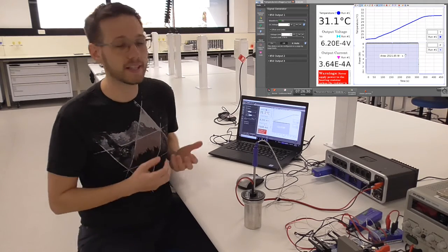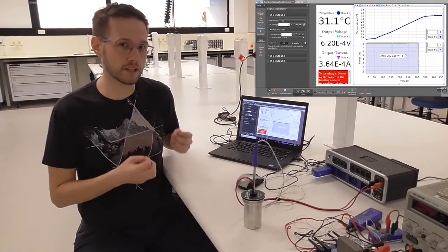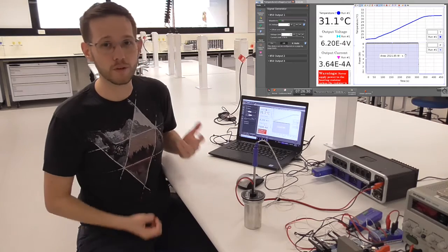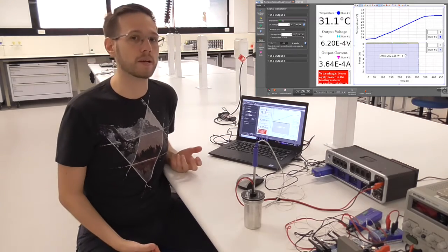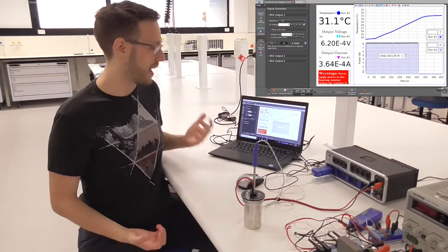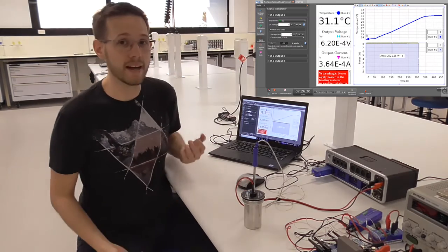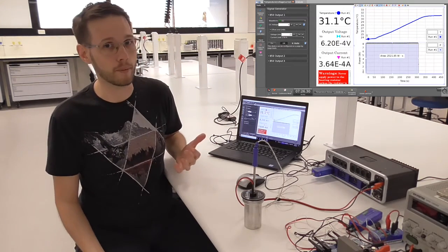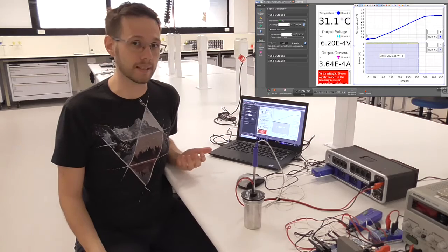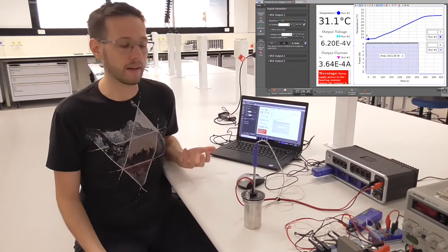So what we need to consider next is how much heat that we've actually generated in the system. We do that by using the equation Q equals mc delta T. We have our delta T values now from the measurements that we took earlier. We know the mass because we recorded it at the start of the experiment, and we know the specific heat capacities, or C, of both water and aluminium.